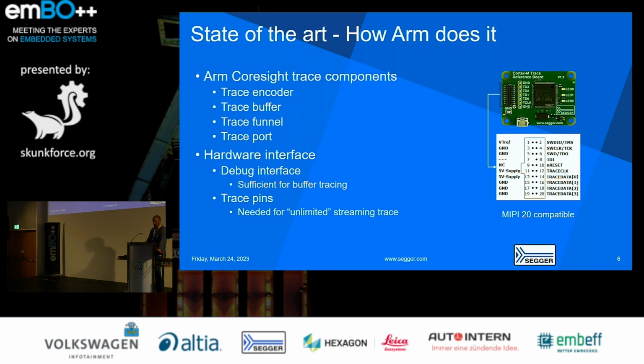On the right, you can see such an example pin interface on a trace reference board. And you see on the pinout, you have your standard SWD and JTAG pins. And this interface is also MIPI 20 compliant. So it's standardized over a very widely used alliance that has been used for many, many years on all kinds of hardware designs. So it's very, very well established.